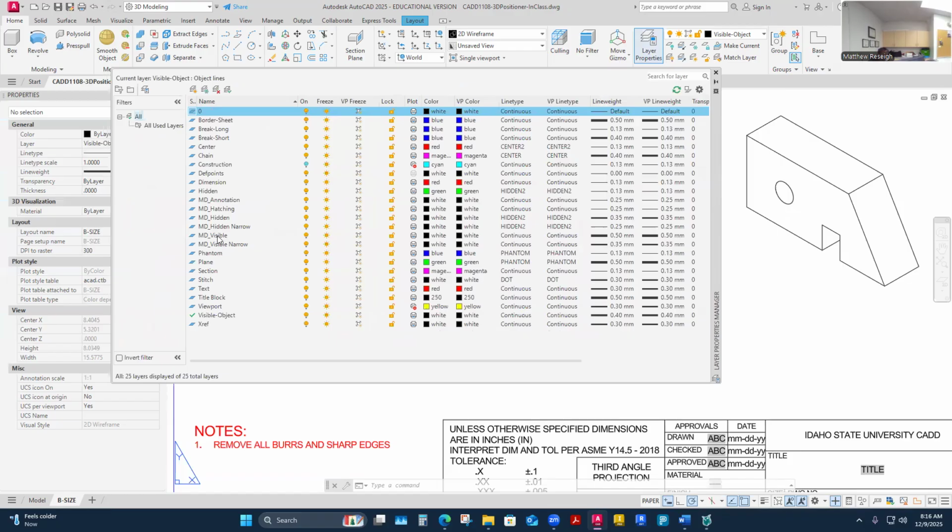I almost have a visible narrow and a visible. I'm not sure which lines are which on that model, which ones would be considered visible narrow and visible. One of them's picking up at a 0.5 millimeter and one's at 0.35 millimeter. I don't usually change these. Normally our visible lines would be 0.4. So I'm just going to leave these as their default, how they came in.